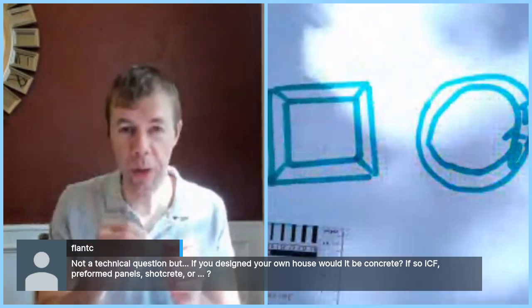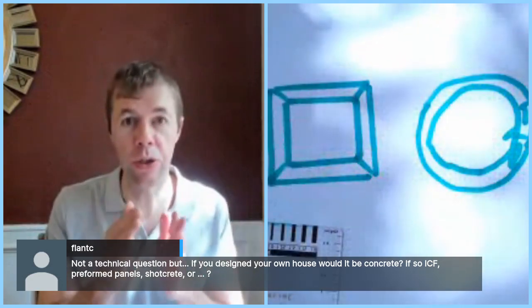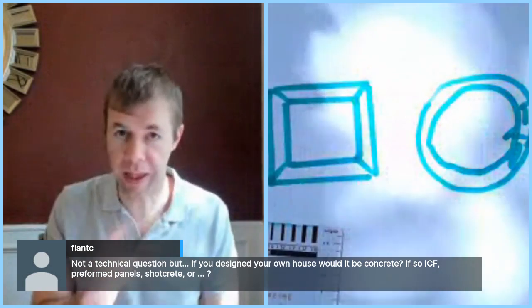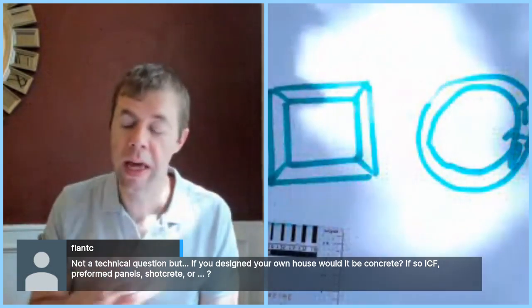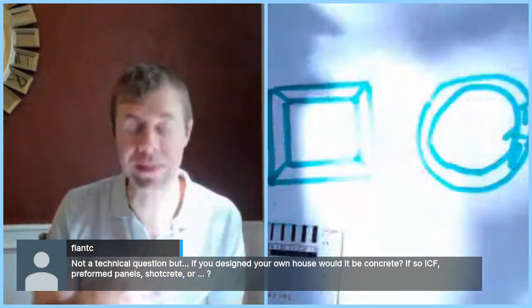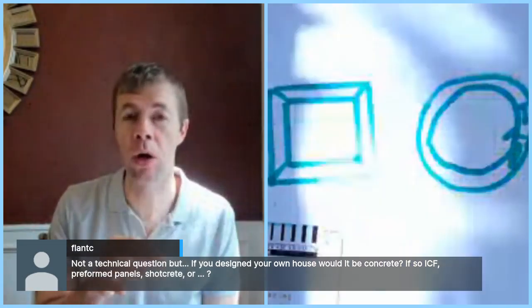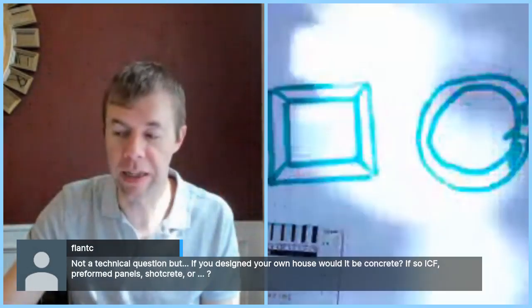So it's like cast in place concrete, like walls and columns, things that people already know how to do, but it has this kind of insulating formwork. Again, I think it can be great, but it can be challenging as well. If I had to choose, where I'm at, I would probably go with panels, because panels are more common locally than ICF is.